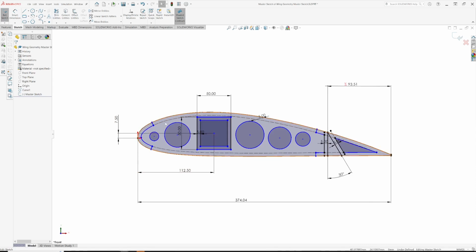We used offset entities to get these offsets, using construction lines, and then we put solid lines to make all our parts. We used some equations to help us use our dimensions more effectively, and then checked everything was watertight by trying to extrude it. Then we created new parts by putting this part into a new part and using this sketch to obtain the geometry we needed.